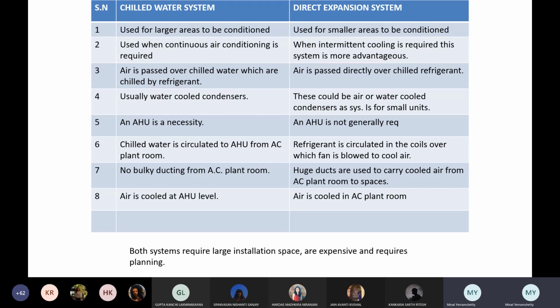So what you do is you introduce an AHU. और AHU कैसे होता है, उसमें पानी नहीं जाता है, उसमें refrigerant ही जाता है. Okay, so you choose a refrigerant, first of all, which will be a little less volatile, which is able to travel long distance, and then it goes to the AHU, and AHU में फिर आप fan लगाते हो and the same thing happens. But ideally what you are saying is, instead of taking an AHU between your Audi and your basement, यानी कि the travel of the refrigerant is lessened. That is the only requirement.